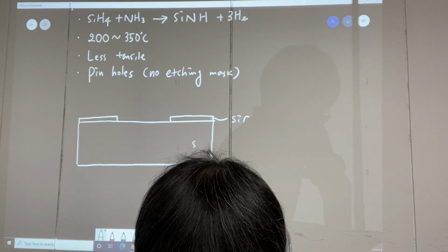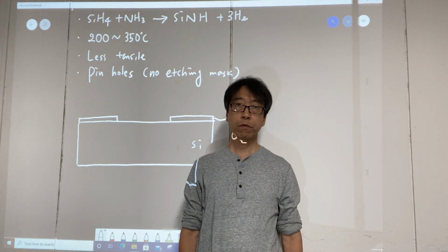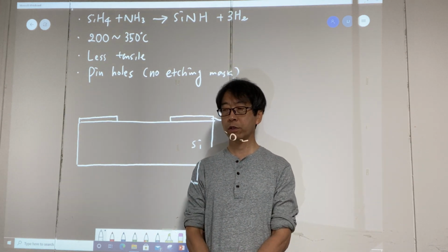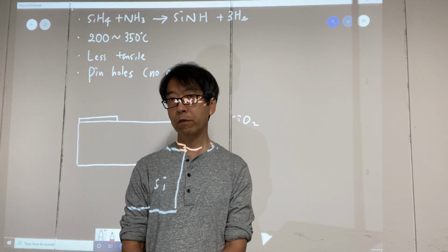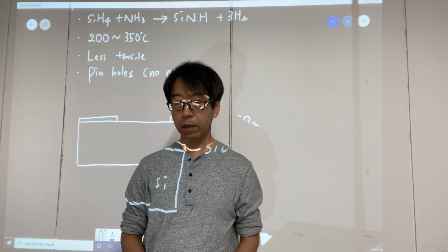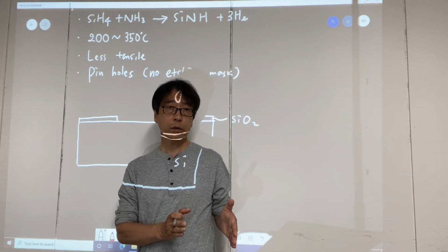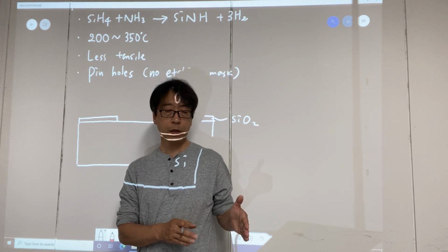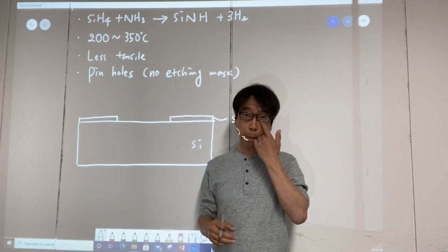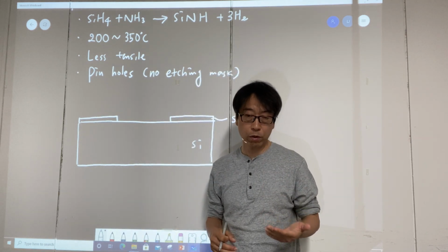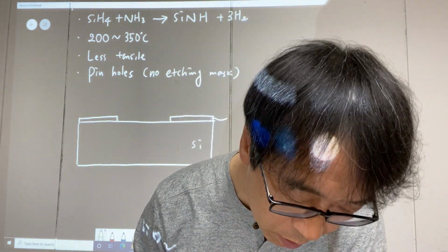How can we grow it? Well, we can use the oxidation process. We've already seen how such a process can be carried out and the physics of this oxidation. At the early time scale, the growth will be linear, and at a longer time scale, the growth will be parabolic, getting slower and slower. We've already seen all kinds of mathematical and physical models of it.